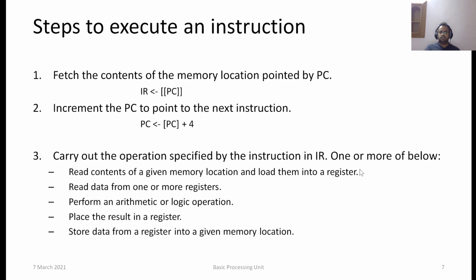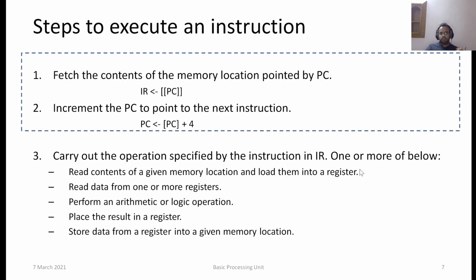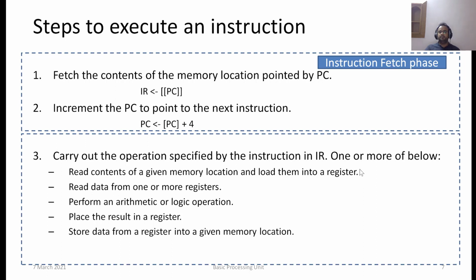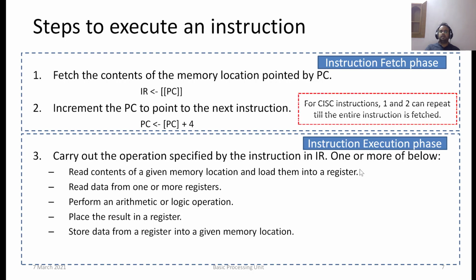The instruction register would be telling us one of these or a few others like the control instructions also. We are going to look at that. Now, how the hardware goes about this third step is what the entire discussion would be about in this module, right? Now, let's go a little finer. Before that, a definition: steps 1 and 2 would be typically called the instruction fetch phase, and the steps in 3 are called the instruction execution phase, right?